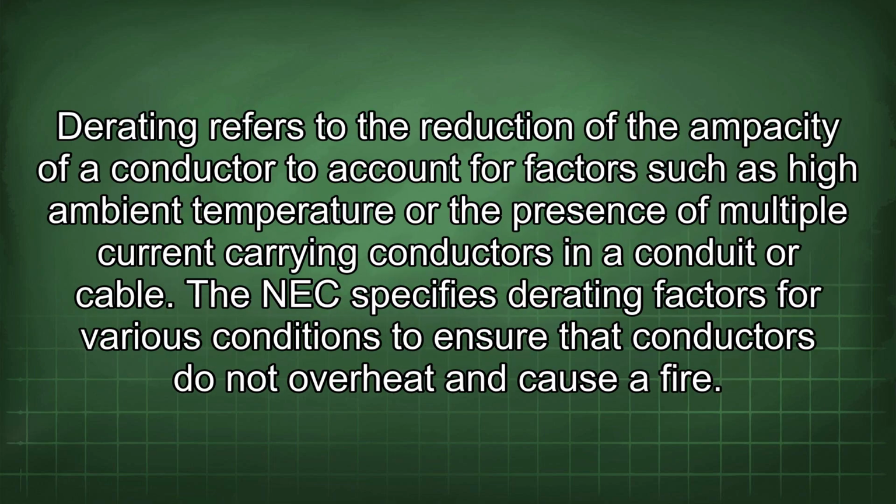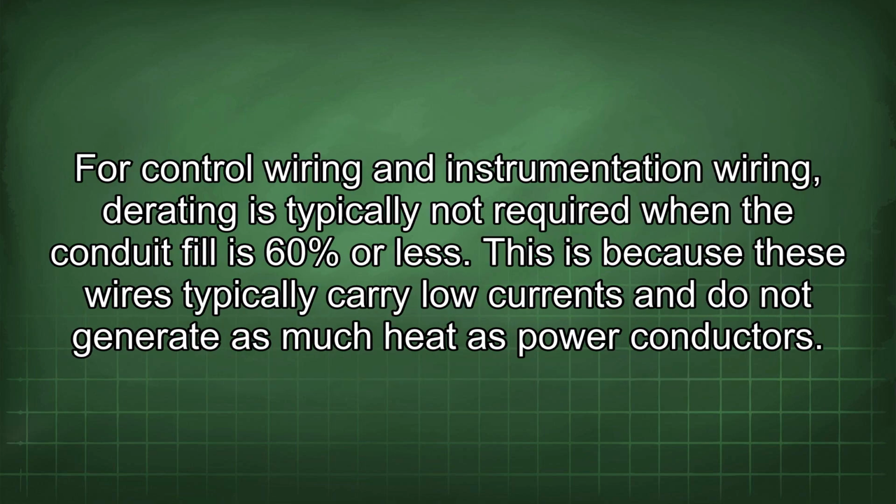Derating refers to the reduction of the ampacity of a conductor to account for factors such as high ambient temperature or the presence of multiple current-carrying conductors in a conduit or cable. The NEC specifies derating factors for various conditions to ensure that conductors do not overheat and cause a fire. For control wiring and instrumentation wiring, derating is typically not required when the conduit fill is 60% or less. This is because these wires typically carry low currents and do not generate as much heat as power conductors.